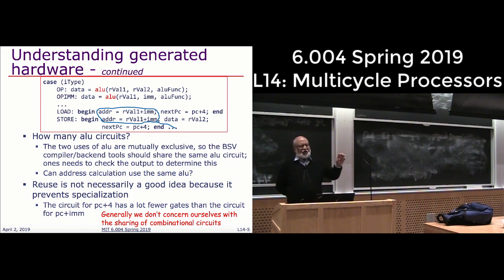If the instruction is op immediate, use ALU. If the instruction is load, perform an addition. Could I have used the same ALU to perform that addition? Yes, because it's again mutually exclusive. Either an instruction is op immediate, or it's load, or it is store.